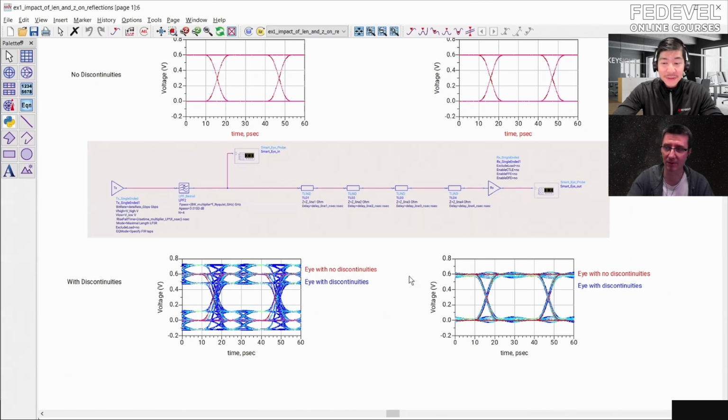It's not important because we are not really reading the signal from the output of the transmitter, but it's very interesting to see how bad it looks. This may actually be very important. Sometimes people may think it really doesn't matter where they put the probe, but maybe they always should measure where they are reading the signal.